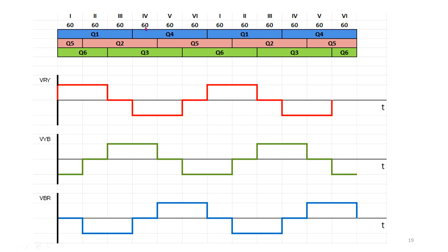since it's 180 degrees, we need to consider 1. This is Q1, and if we suppose it has a relation, you can easily construct those from here. Okay, since it's a 180 degree voltage source inverter, it's a conduction sequence of one, and you can see that each thyristor, when it is conducted, it is conducted for 180 degrees.